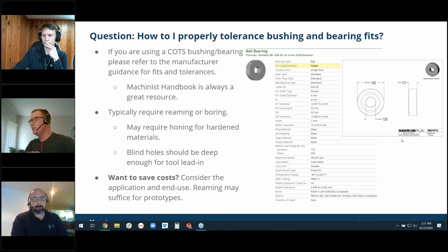So if a ball bearing is being pushed over the outer diameter of a shaft, what is an acceptable tolerance range for the shaft? If it's going to be pushed into a circular pocket and retained on the outer race of the bearing, what size should that pocket be?